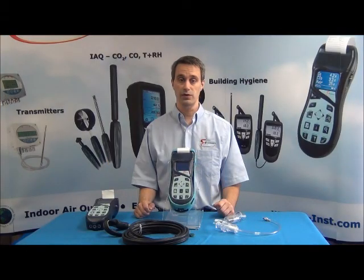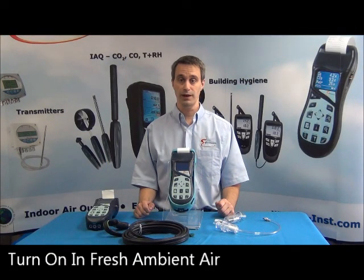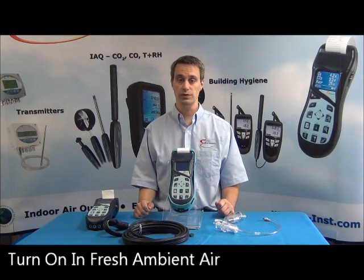Also, it is recommended that a unit is turned on in a fresh ambient air environment, as the units actually auto-calibrate themselves every time they are turned on. Being in fresh air and not having any of the probes plugged in will ensure that the unit is clear of combustion byproducts and calibrated properly for accurate testing.